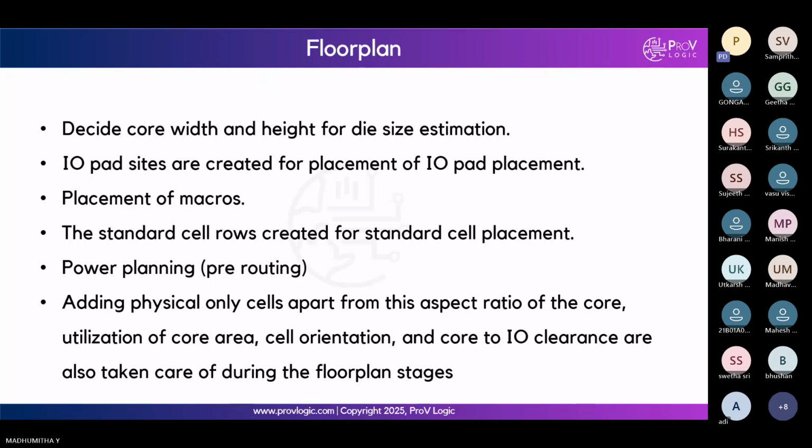Each synthesis engineer will generate 10 netlists, and after generating them, they will push them to the physical design team. Depending upon the requirement and the functionality of the IC, this work will be segregated. But keep in mind that physical design starts from synthesis, and then only we will start with floor plan. I'll explain what we will do in floor plan.